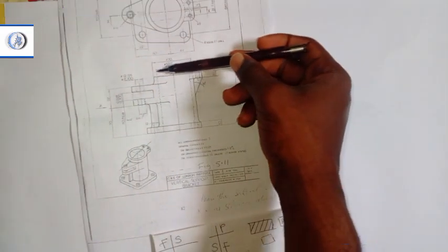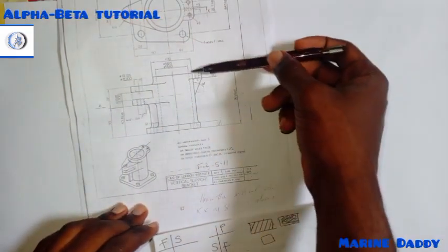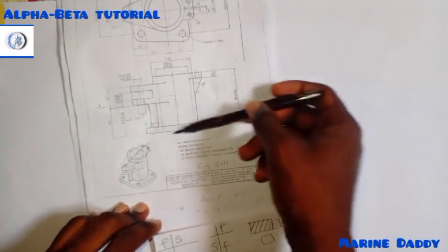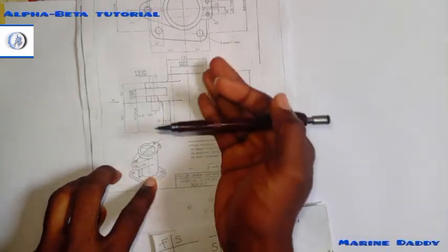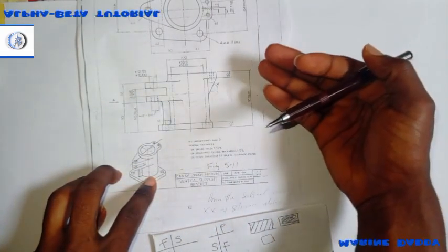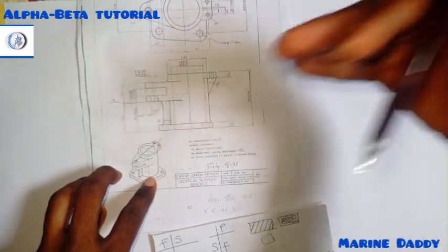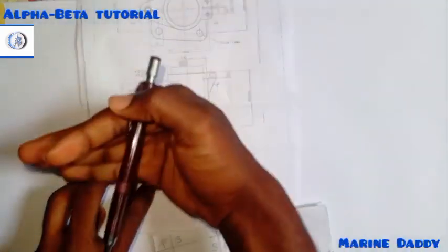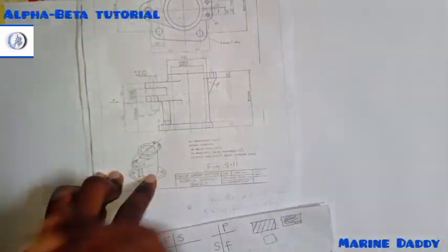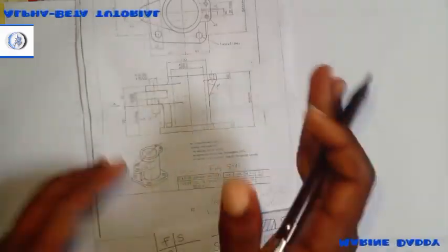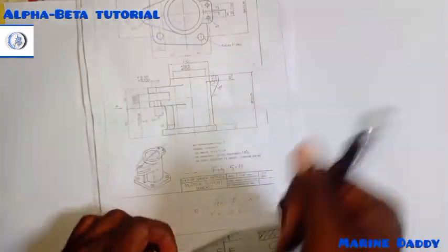Okay, what you need to do is produce this out first. After drawing it, when you divide this, the parts that are affected by the cuts or by the cutting plane, the imaginary line, you use your diagonal line to shade it, while the part that was not affected you leave it like that, and that's what we are trying to do.